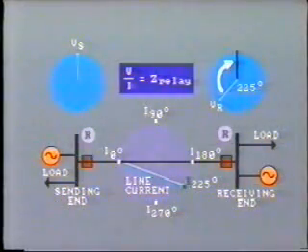The impedance increases because the current flow in the line is now decreasing again as the swing continues. At the receiving end, voltage is now beginning to close in on the sending end voltage and so reduce the angular displacement. It's clear that the application of the out-of-step relays varies for each specific condition and location throughout the power system. You should take time to examine the installations in your own power system and work out with your supervisor the rationale for each case. What are the relay settings? What do they do, and why?